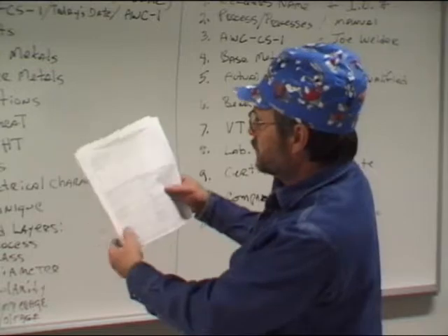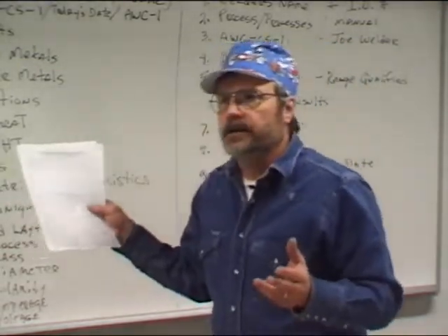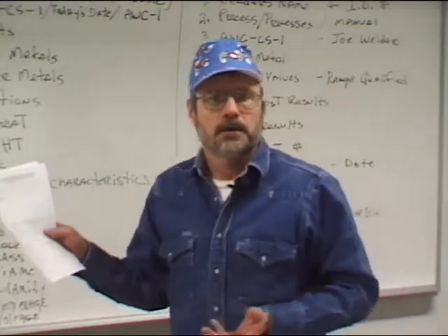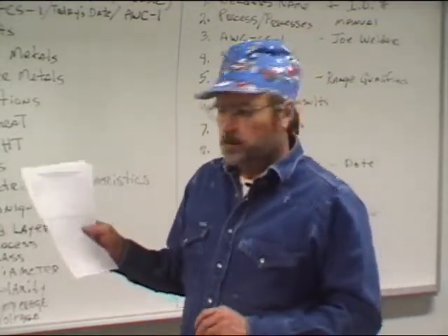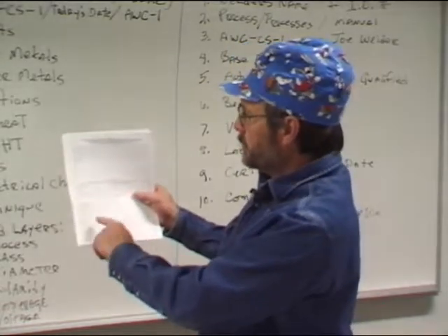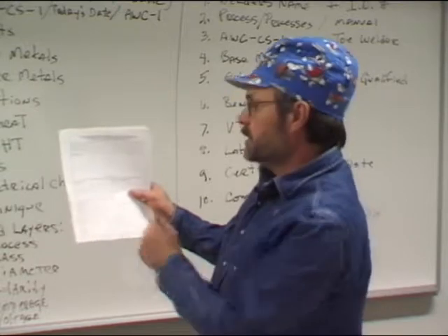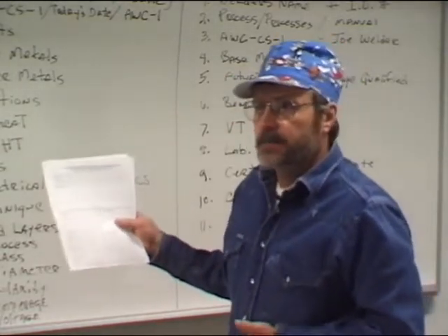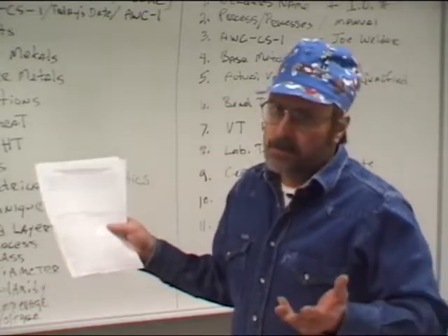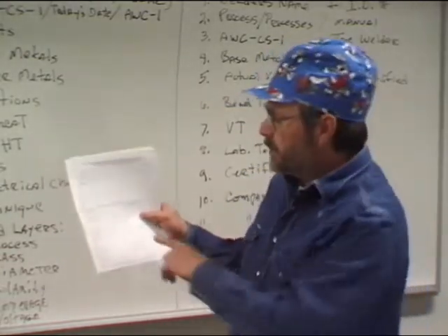So next we go size of filler metal. Well, what size welding electrodes did we make that welder use? For the root pass, we'd probably make him use a 1/8 inch 6010. So that's what we would write here where it says size of filler metal, write 1/8 inch. And then to fill it and cap it, typically 6 inch Schedule 80 pipe, you would stick with a 1/8 inch, but you might also allow him to use a 3/32. Whatever you decide is what you have to write in there.